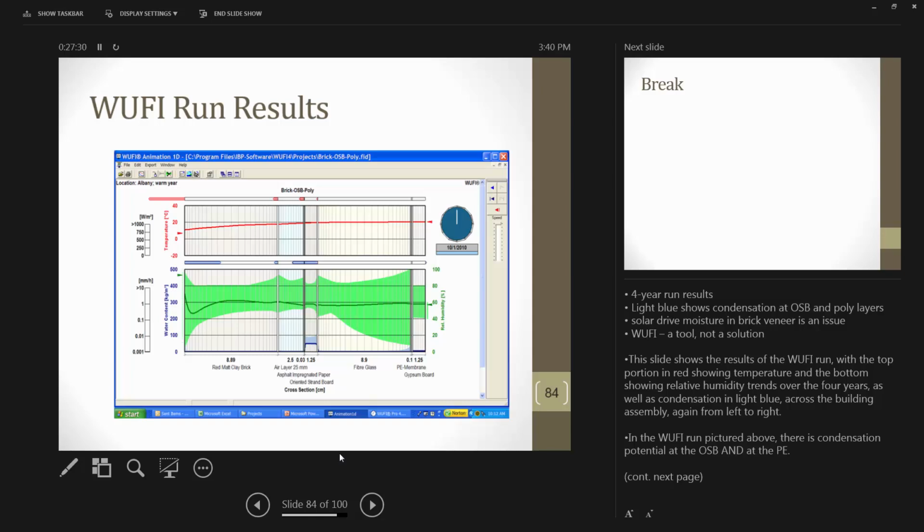So that's the first part of it. We'll wrap it up there. When we're looking at system design, that thermal envelope is the biggest system, and it's the first one that really needs to be evaluated, to at least create your baseline. So now as you're designing and evaluating your other systems, you have something to evaluate against. And we'll talk about the other systems, various changes that we can make for efficiencies and how they're going to affect the envelope and how envelope changes are going to affect the other systems, and so on and so forth.